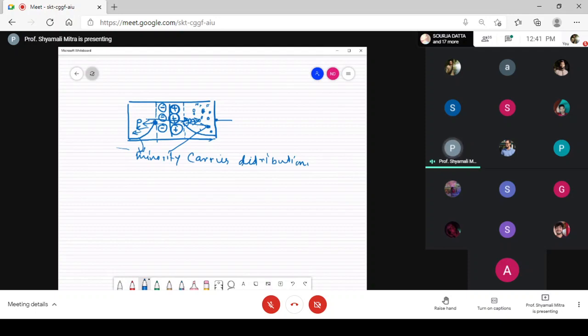Now, thus before recombination, what we want is to harness this property. So we definitely need a third terminal. You can see here that the minority carrier distribution always decreases as it goes away from the space charge region towards this end. Now, what to do? In this condition, we can add here one more terminal, so that just before getting recombined or being lost, they can be harnessed to some other regions. So let us try to put a third terminal first, then we'll discuss these pros and cons after that, and we'll try to resolve those factors.